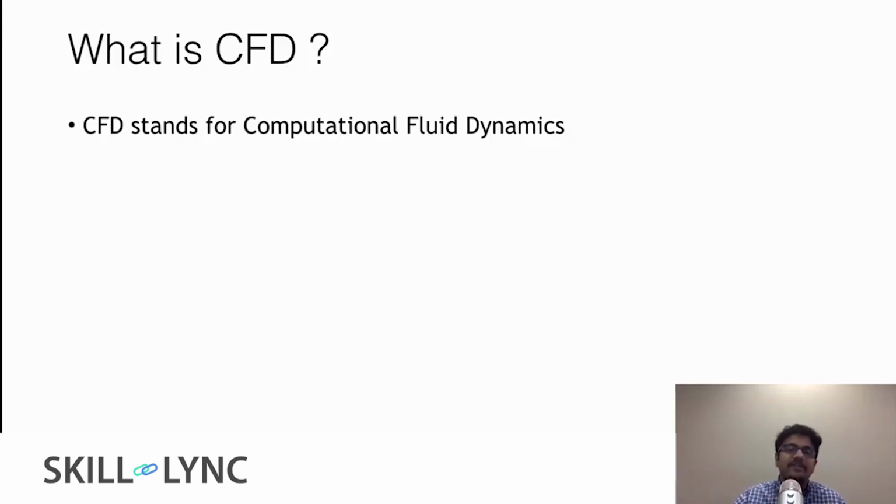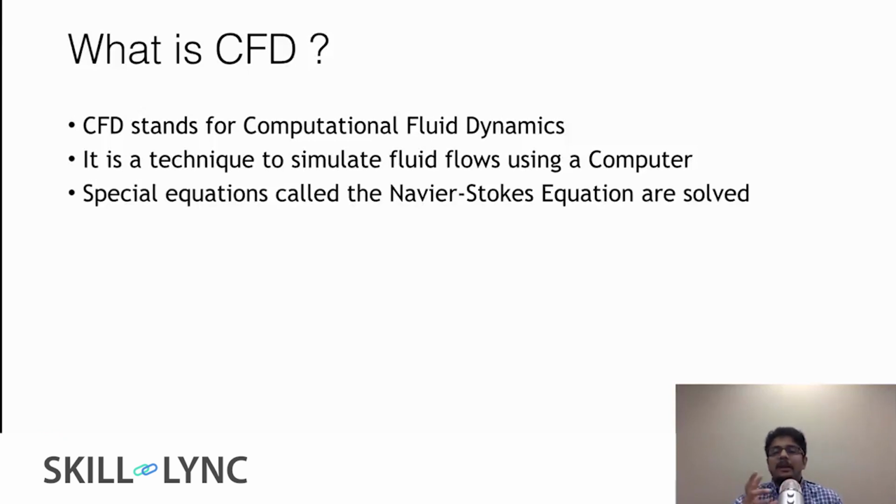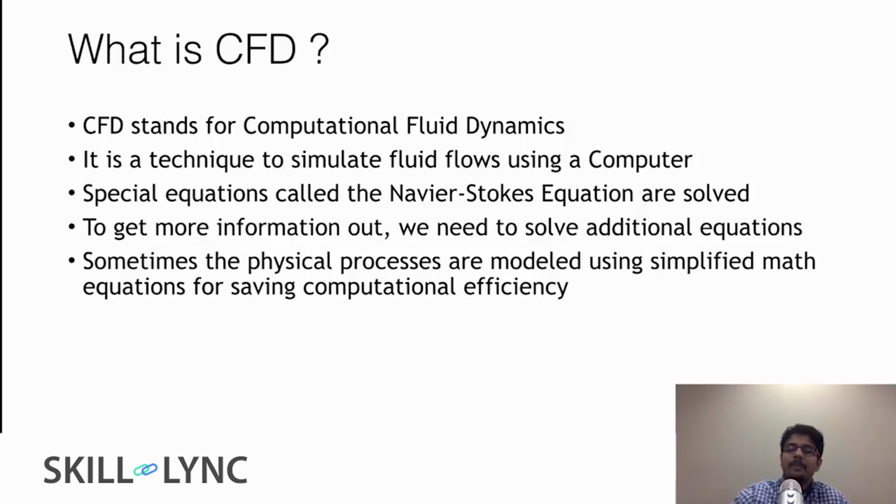So as you all know, CFD stands for computational fluid dynamics. It's a technique that allows you to simulate fluid flow using a computer. Primarily, we solve equations called the Navier-Stokes equations. We'll be taking a look at them. And then to get more information out of the simulations, you need to be solving additional equations. And this is typically the case when it comes to an engineering application. And sometimes the physical processes are modeled using simplified math equations for computational efficiency.